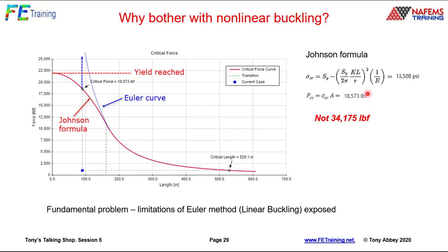Again, the Johnson formula is universal for a large class of well-known struts, beam shapes and so on. It's well proven from theory and lots of test evidence. In civil engineering in particular, it's well established. If we've got a general shape solution, we don't have a Johnson formula for that. We've got to go in and explore that. So if you're not sure, you think you might be here, then you should be really running a comparative nonlinear analysis just to show what's going on.